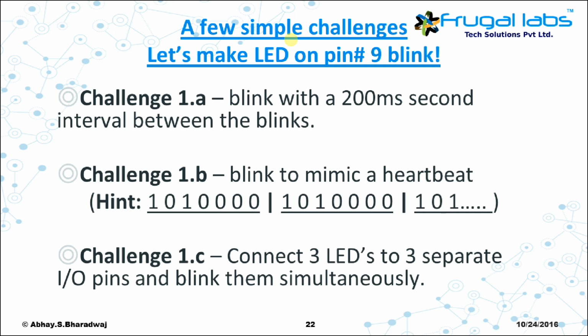Challenge 1A, blink the LED connected to pin number 9 with 200 milliseconds interval between the blink. Challenge 1B, blink the LED connected to pin number 9 to mimic a heartbeat. The hint is heartbeat pulse. High, low for a long duration. High, low for a long duration. So repeat this process. Let's see how we can do it.